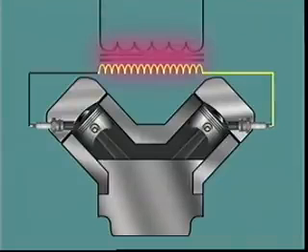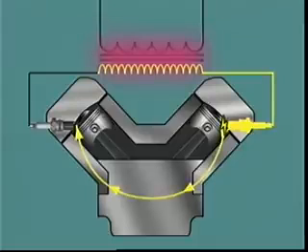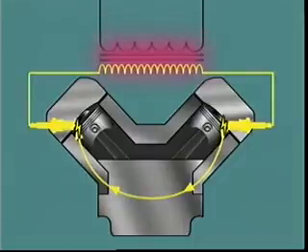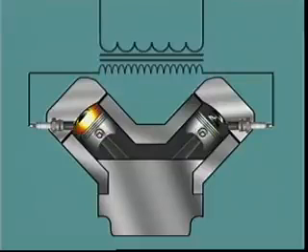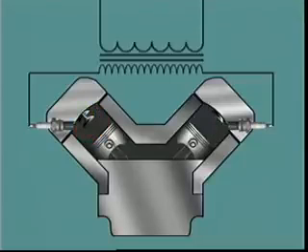current flowing through the high-tension lead to the center electrode on one spark plug, bridging the gap and creating a spark in that cylinder, traveling through the cylinder block, bridging the spark plug gap in the companion cylinder, and flowing back through that high-tension lead to its starting point. The cylinder on the compression stroke with its charge of fuel and air is fired by its spark, driving the piston down on the power stroke, while the spark plug of the cylinder on exhaust simply serves to complete the